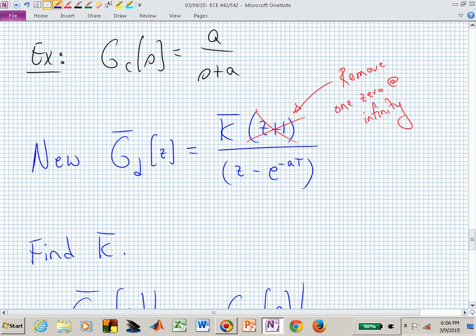We are changing the zero structure, and the zero structure, as we've learned in continuous time systems, usually shapes the output response. So we may be shaping the output response between the first difference equation implementation and the second, and obviously we are. Because in the one, we are using a little bit more information each time we generate an output. We're using 2 inputs versus the second one, where we're just using 1 input to generate the next output.